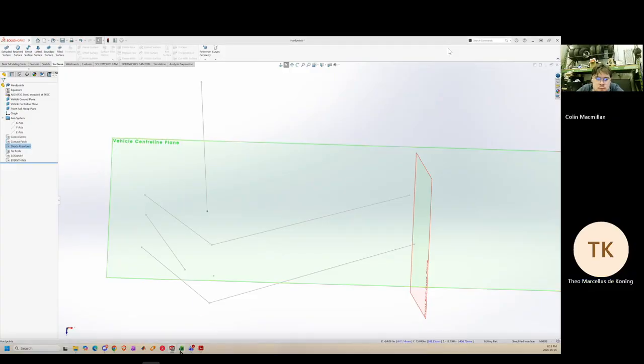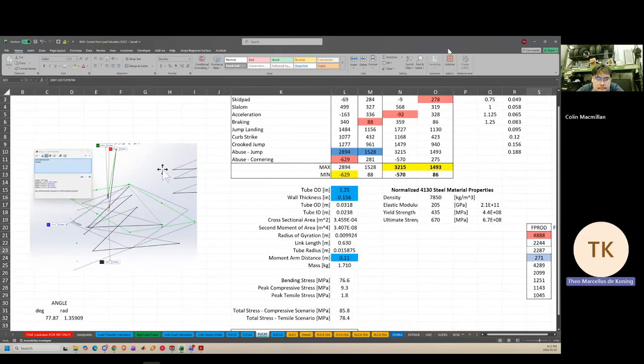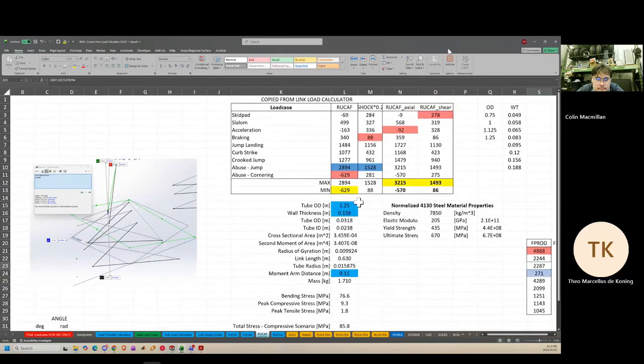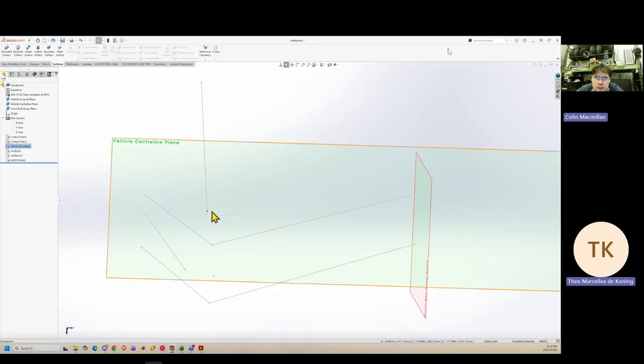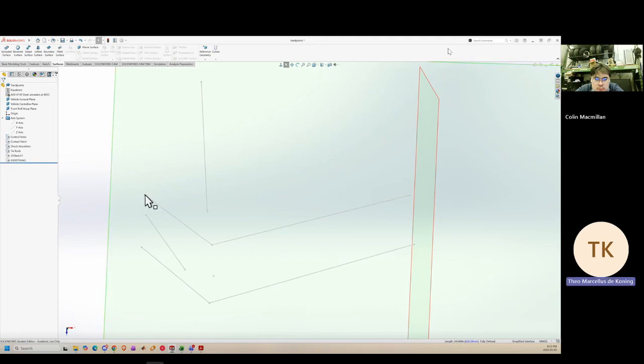Yeah. So for the rears, what do we do here? Basically, the moment ratio lever arm is 3-to-1. So from the shock to the fore link is 3 times longer than to the aft hard point.